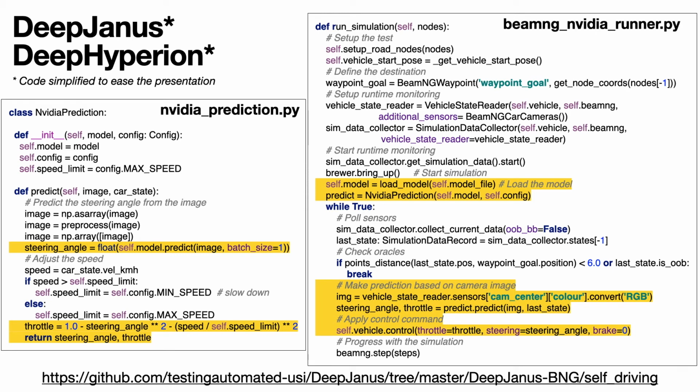and then inside a big while loop, you get the data, for example data from the camera, and then you ask this model to make the prediction. And once you have this prediction, you can apply the control command. Once you have applied this, you can resume the execution of the simulation. We are still running in synchronous mode. Then the control will be applied for the next control cycle, and then you come back after you collect new data, and then you repeat.